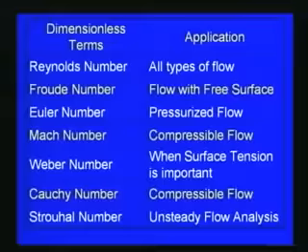And Mach number is considered especially in aerodynamic flows. Wherever compressible flows are important, there we consider the Mach number. And Weber number is concerned especially whenever surface tension is important for the fluid mechanics problems; wherever surface tension is important, we consider the Weber number. And then Cauchy number also, wherever the compressible flow is considered, we consider the Cauchy number.